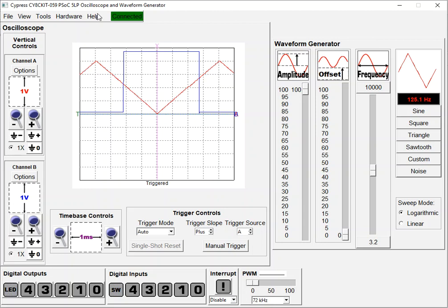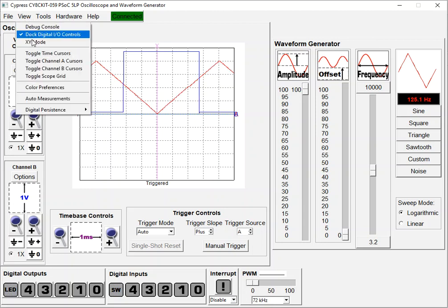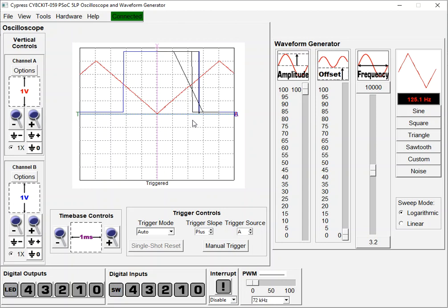point there. So if you want to see that, you can go to XY mode, and basically the X axis is V in and the Y axis is V out, and it will follow a different path from high down to low than if you're low and you go to high. And that's a bistable state, and that's what all the stochastic resonance for this circuit is based on.